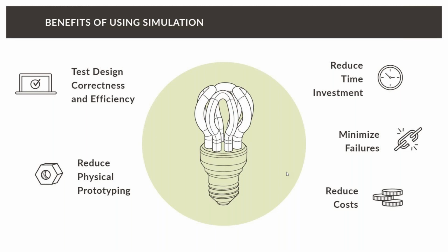the right data. A lot of times people are only talking about the CAD data and they totally forget that the CAD data is only half of the description of your model, and the other half is based on boundary and initial conditions, for which you definitely need data. For example, when it comes to a pump, you're usually not only interested in the size of the pump, but also the flow rate which it can release, and the energy needed to operate the pump.